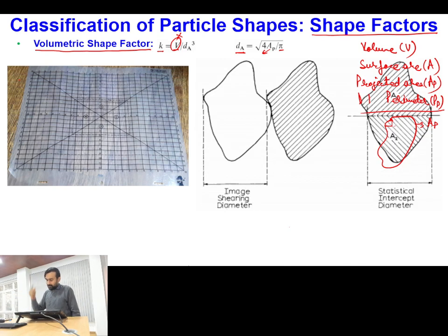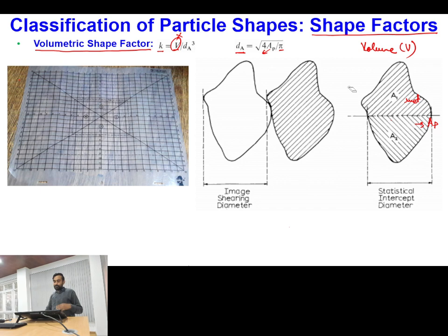So there is another improved approach which is proposed. In the first improved approach, you have to take two images of the particle projected area, and you have to superimpose both the images one over another, and then you have to start displacing one image such that it is just making a line contact with the outer boundary of the other particle. Okay, so like this. First both these shapes were superimposed over each other, and then I slowly started moving this.